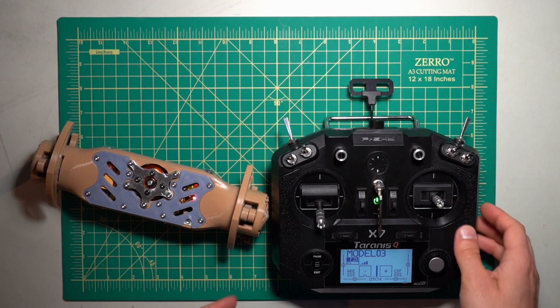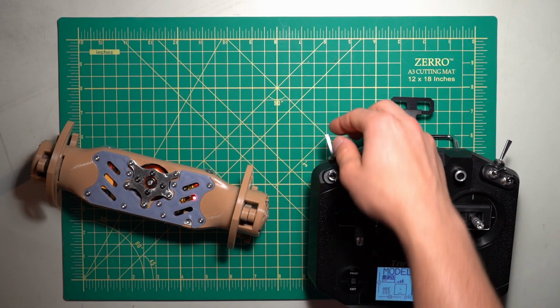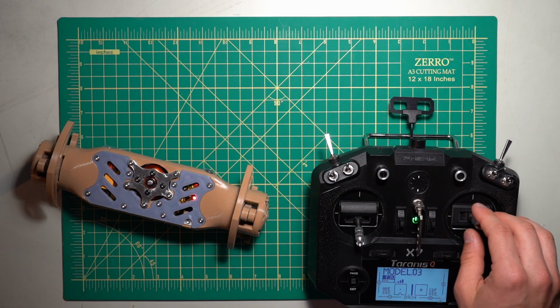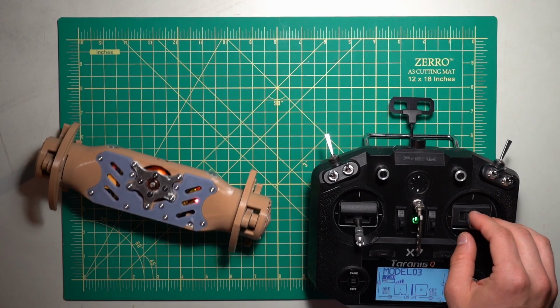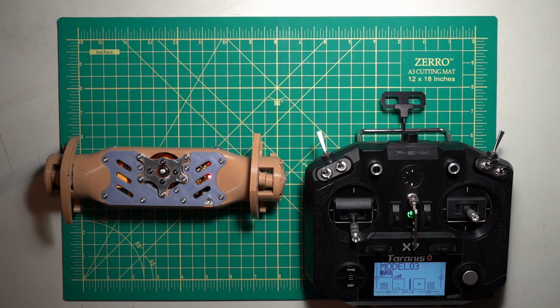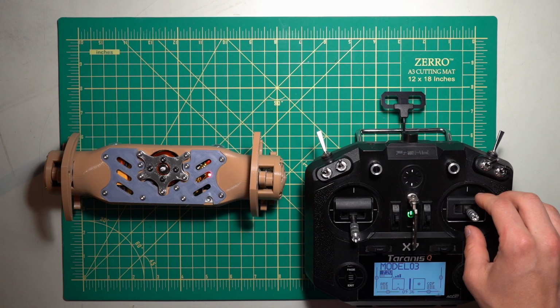I don't have a servo on this robot, but I can see that the safety properly overrides the weapon motor, and that the drive motors work correctly going forwards and backwards and turning left and right. What if it doesn't though? I've gone in now and messed up something in my robot on purpose. Now, when I try to go forward, it turns.